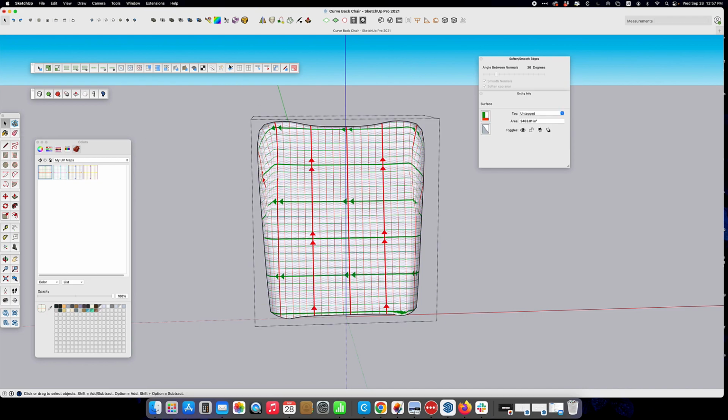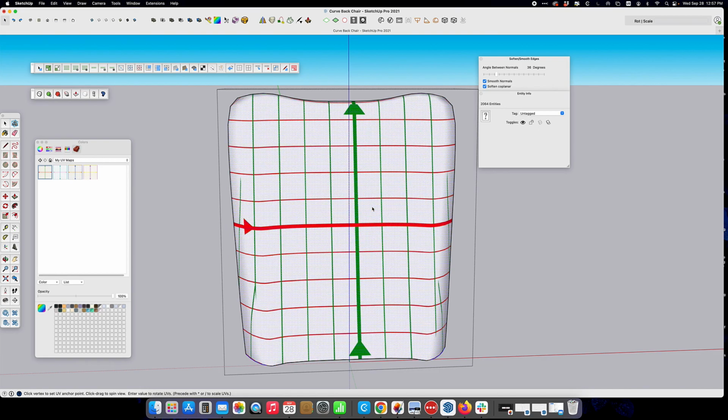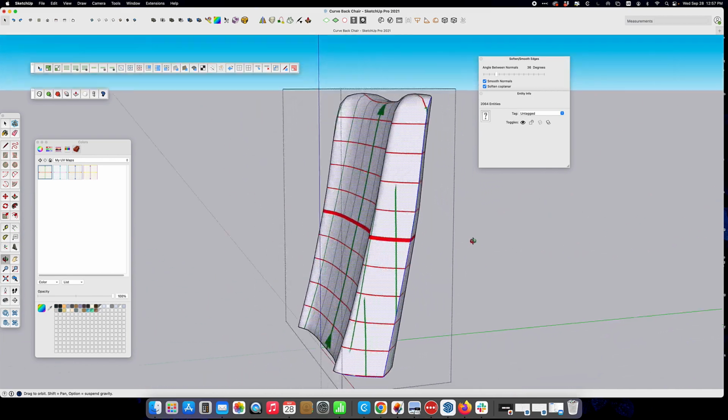What I do is I put the texture on, I set it using the natural UV map using ThruPaint, then I go to SketchUV, and you have to have your surface selected when you do this. So right now it's not selected. Right now it is. You can see it's kind of dotty and spotted looking. I click on the SketchUV button and I get this cursor with a circle arrow thing. Hover over my surface, right click, and I select box map. That makes things look pretty good all the way around.